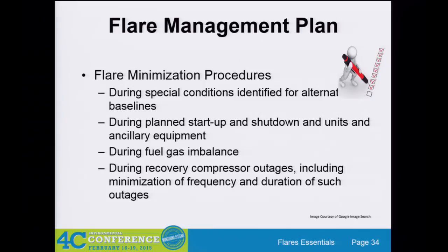The planned startup and shutdown of units. Basically, they said if you create written documentation of your startup and shutdown procedures, and those procedures take into account minimization of flow to the flare, if you're following your procedure and you exceed your RCA threshold, you do not need to do an RCA.